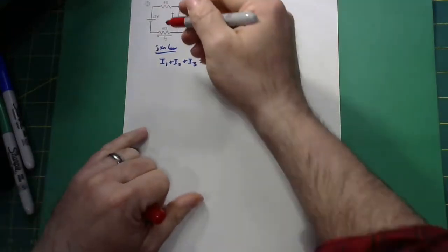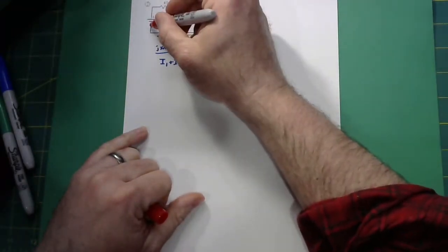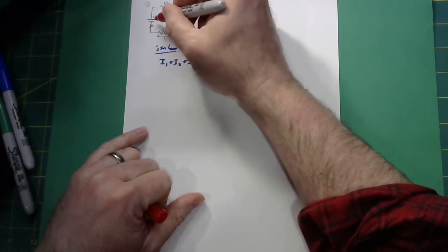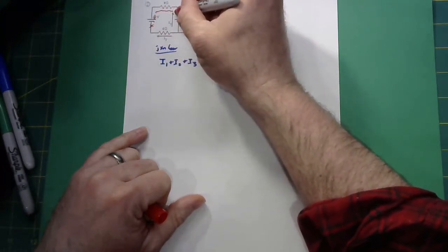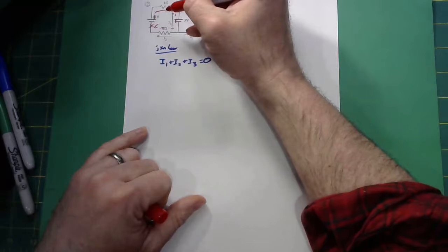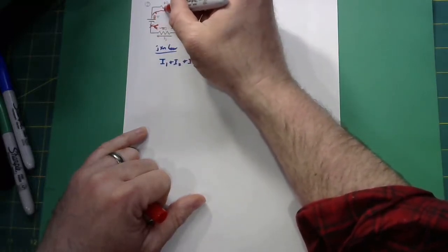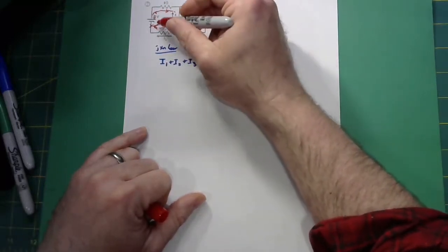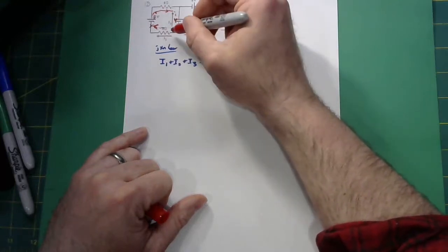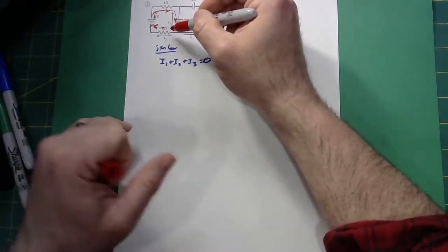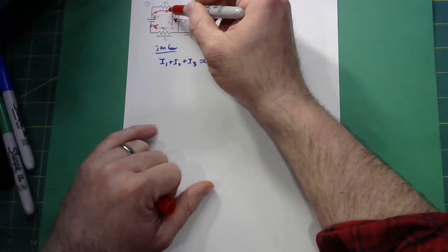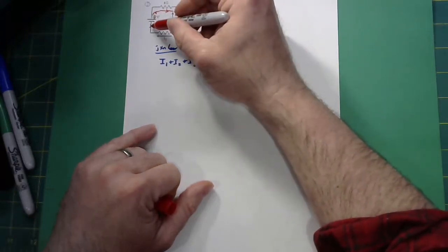So we will go ahead and do a loop on the left side. Again, I'm going to start at the low V side of that 12-volt battery, right? And go, right? Okay, and again, I'm going around the circuit. I'm choosing to read the circuit this way. I'm not necessarily saying that I2 is going to go in that way, although it is in this one. But I'm just choosing to read the circuit going clockwise. So first, I'm starting at the low V side of the battery.